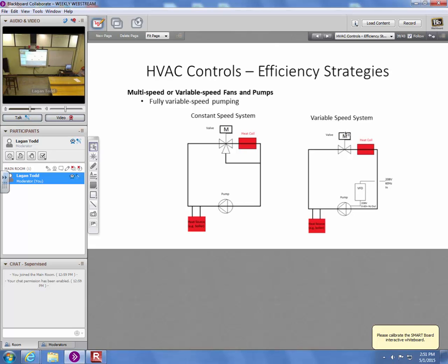If you put a 2-way valve in here, and you don't put anything on here to control the pump speed, when you run this pump and you don't want heat here and you start to close this valve, now the pump is pumping through a more closed valve. Actually, I shouldn't say it works harder, because it actually works less hard. But it is pumping through a more closed valve. I'll show you that on a pump curve in a minute. But it's not the efficient way to do it.